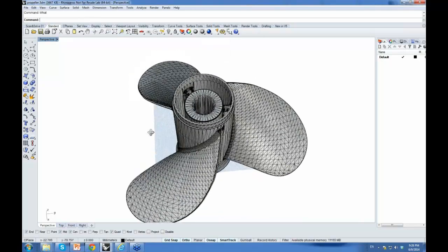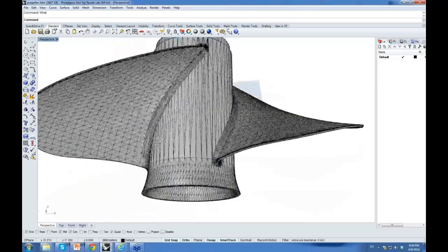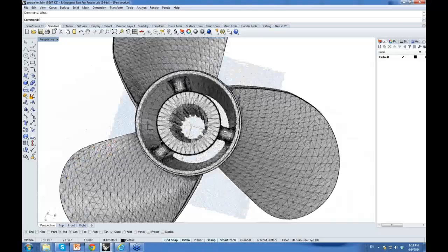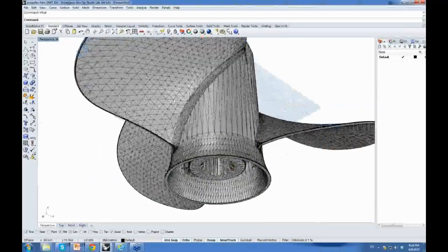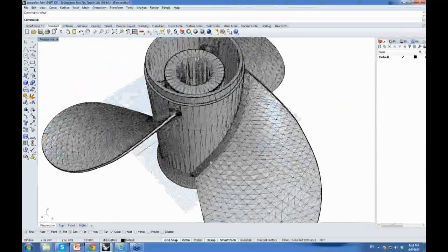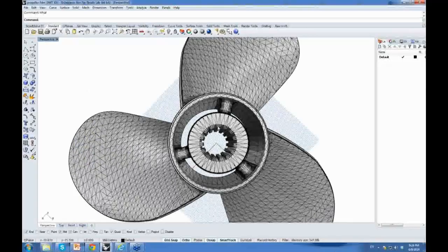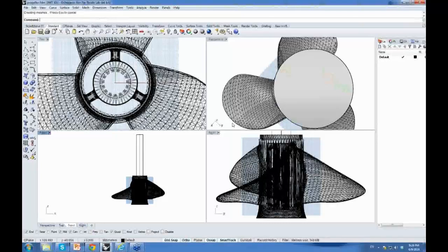In order to do analysis on this, we want to simulate the thrust load on these blades due to this propeller moving through the water. So we'll restrain the spline on the inside and then apply a load on the bottom faces of these blades. To select the spline surface, we could go there and individually select all these triangles, but that's kind of a pain. So we'll use the insolid command, which is new for Scan&Solve 2014, and the mesh operation.